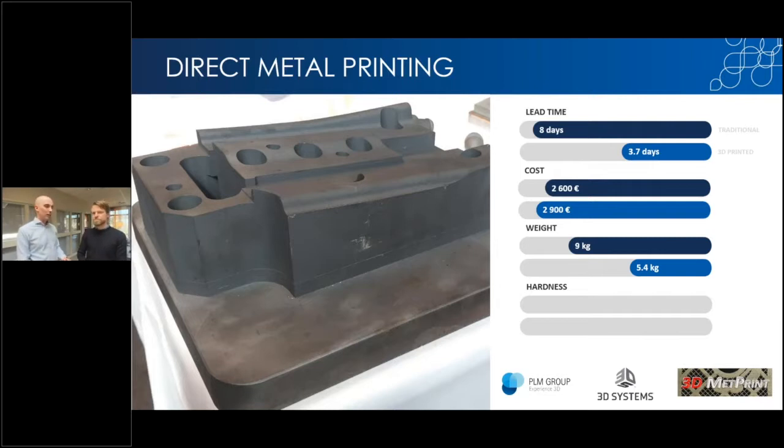And the hardness of the tool: the hardness they have today is 60 HRC, which is on the Rockwell C scale. And we were able to harden it up to 57 HRC, which was more than enough to have it in production. Nice. So this is actually producing cars as we speak. Really impressive. Excellent. So it can be used for tooling as well, obviously, to improve lead time, performance and weight.